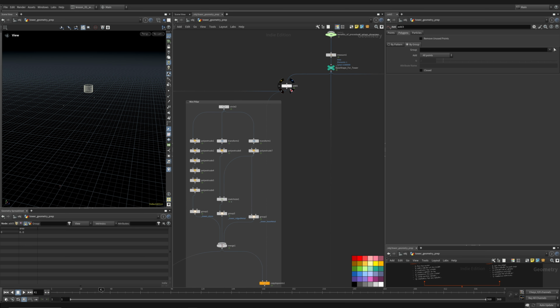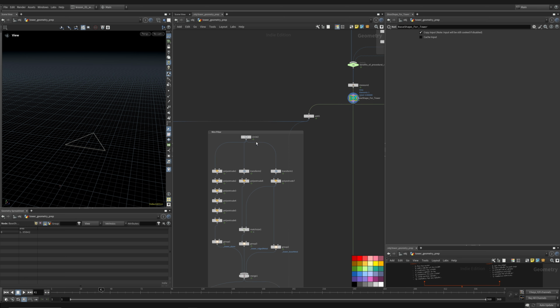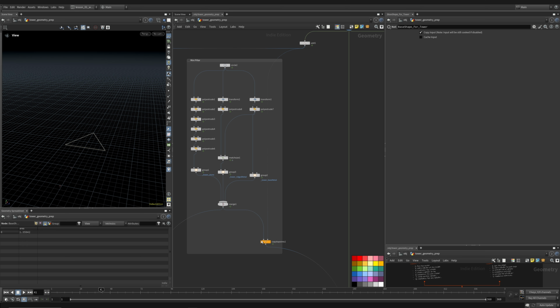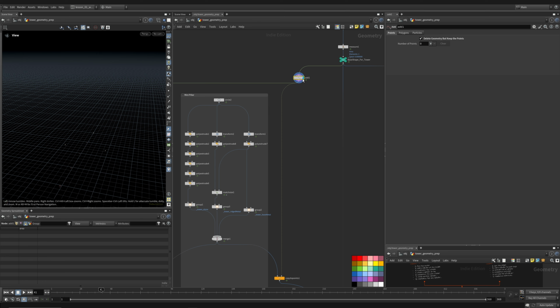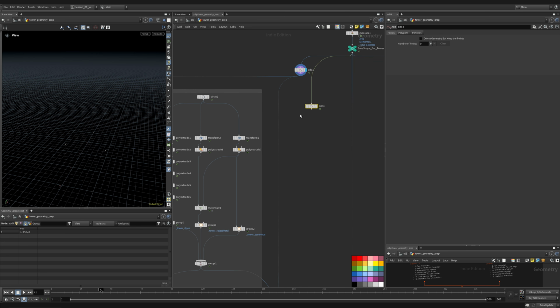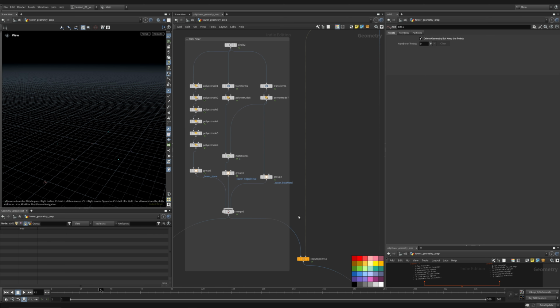All right, to continue, we are going to go back up to the next part and make our main pillar. So for this one, we create the centroid, or we get these points. Another thing you can do with adds, you can do a lot of things, but a funny thing you do with adds a lot of the time is delete geometry with an add. A little bit counterintuitive, but that is very, very commonly done. So we delete geometry but keep the points, which will delete all those other parts we don't need.